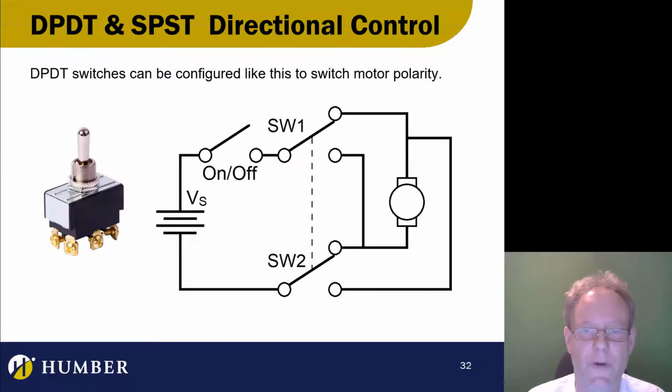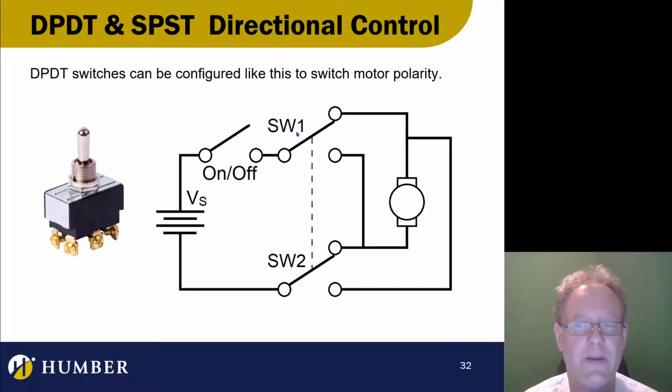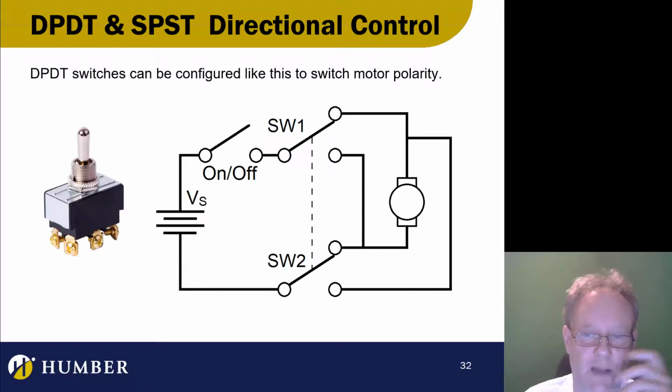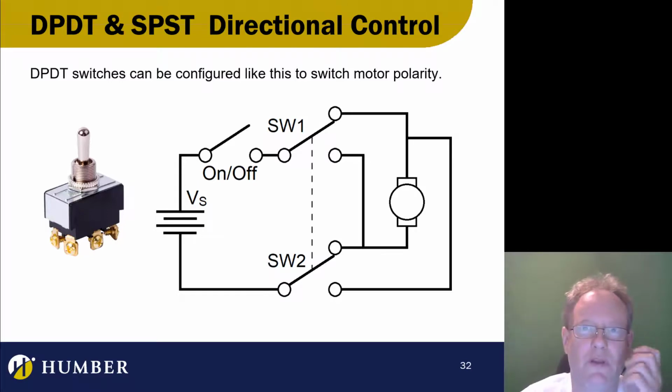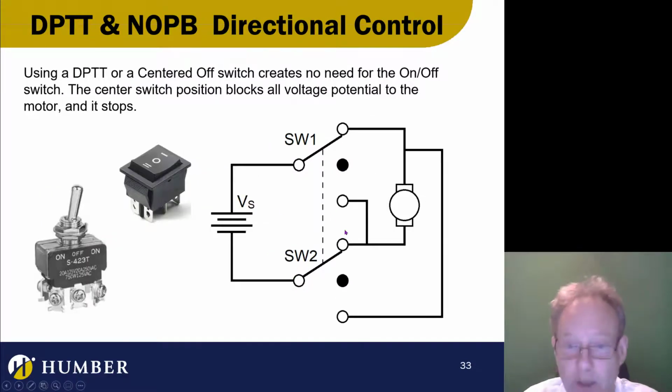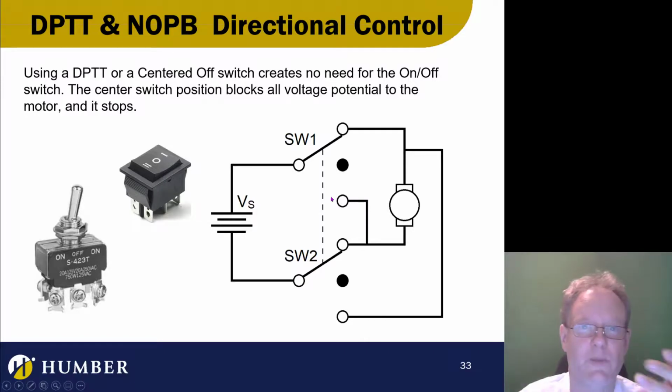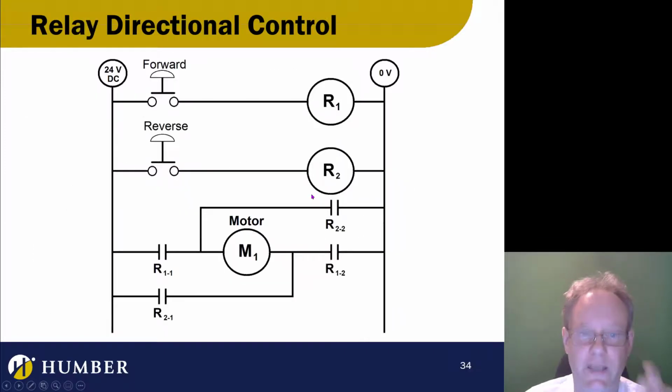Okay, good. So in this situation, you can do that as well. You can do a flip back and forth quickly and mess your motor up. But if you look here, there's no way to turn both forward and reverse on at the same time. You can't unless you toggle it really quickly, back and forth. It's really confusing for your motor, but you wouldn't do that. Same thing with here. So the only problem with this circuit is you can switch the polarity really quickly. It's a problem.